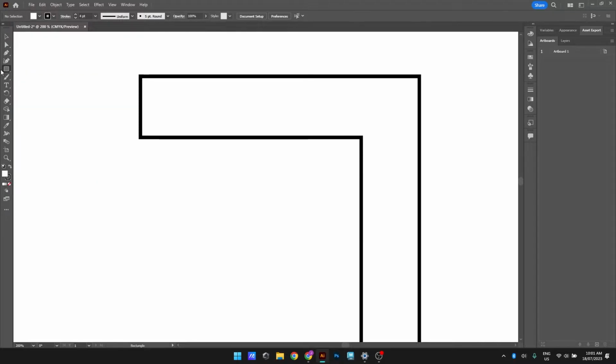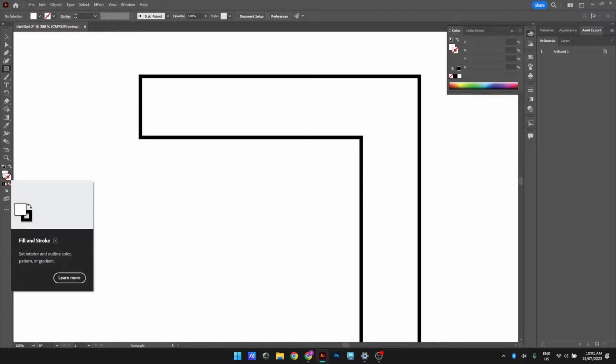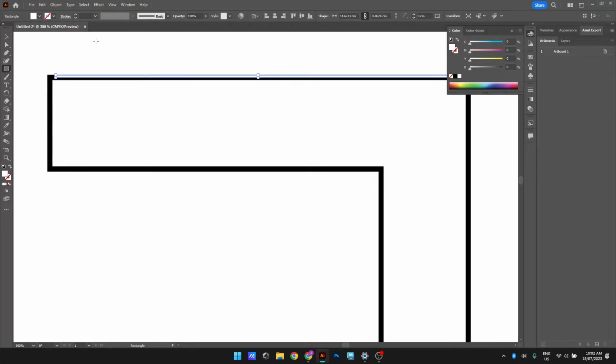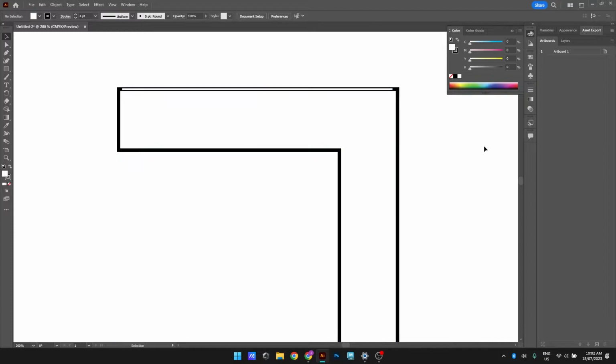I want a long window the whole way along this face. So I'm going to use the rectangle tool again. Over here on my color, I'm going to leave it white, but with the stroke, I'm going to click this little remove button. So you can click on that stroke, click the remove button, and now I only have a white fill. And where my window is, I'm just going to draw a long shape along there, back to my black select tool, click on it, and I can drag it down and have that centered in there to look like a hollow space for now.